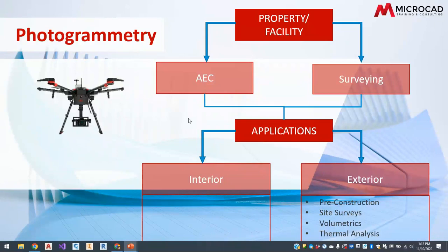And then, as I had mentioned, for the power plant thermal analysis, the different payloads available to the drones is just astounding. You can put some really powerful equipment on the drone and use them in a lot of different scenarios. So we have the photogrammetry, we have LiDAR on board, and then we have thermal cameras available, depending on the application.